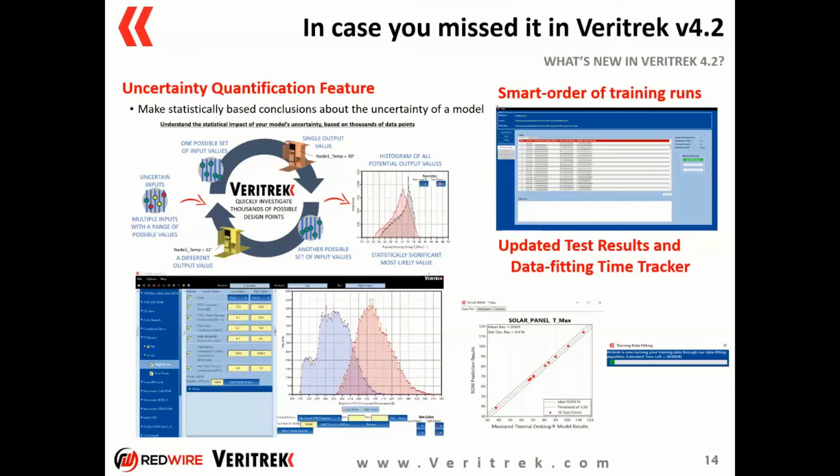So in some cases, we may have symbols or input parameters to our Thermal Desktop model that have some uncertainty as to what their actual value will be. If we're getting the variable values from a handbook, maybe there's beginning of life, end of life situations with our input parameters. There's some uncertainty within our thermal inputs, and we want to understand how that uncertainty propagates to our output responses. And that's what this new analysis feature allows us to visualize and understand.